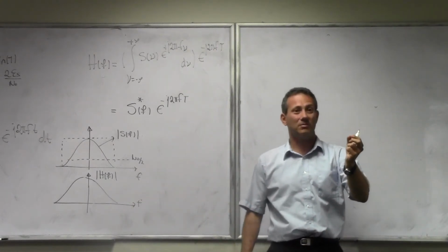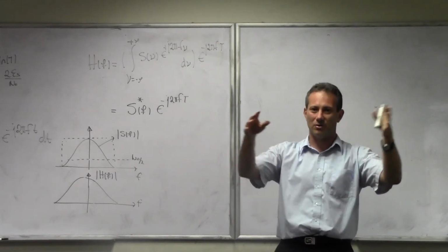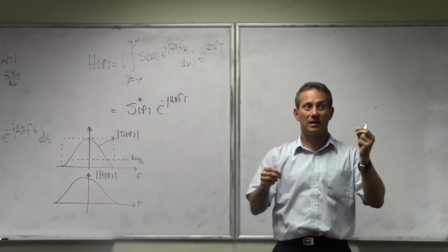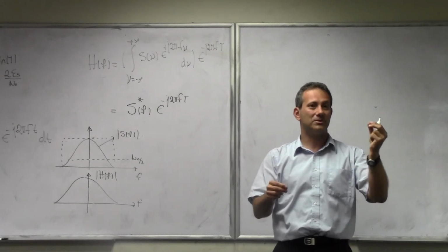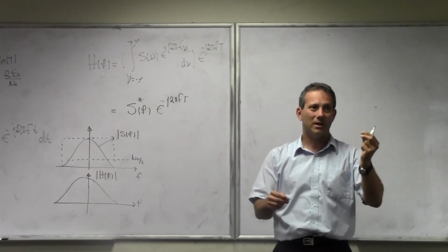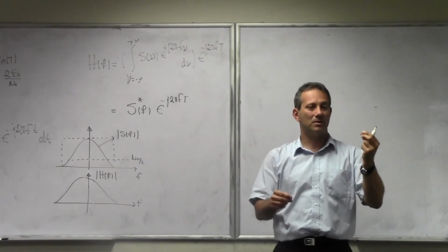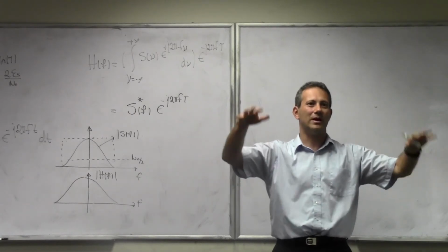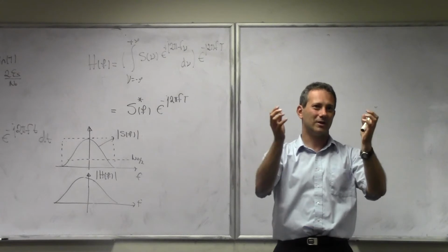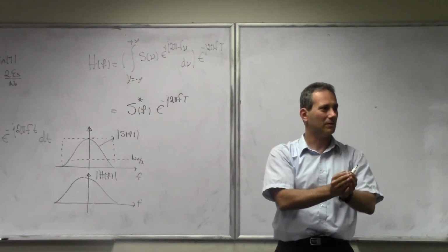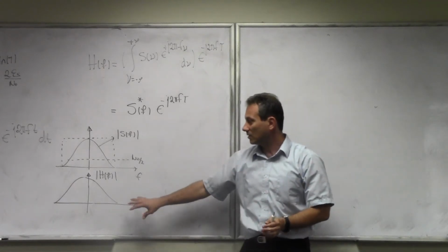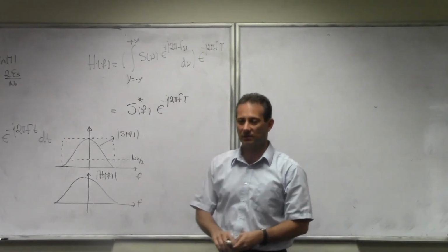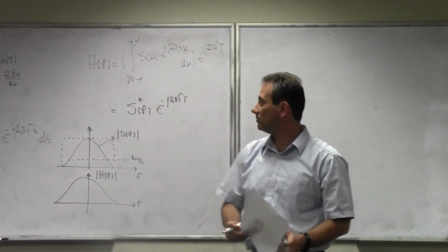And that's always going to be the case in a lot of problems that you encounter in various courses. You're going to find the task of maximizing signal to noise ratio. That's a really different task than preserving the signal. And whenever you try to maximize signal to noise ratio, it's always: where is it good? Give me more of that, and where it's bad, give me less of that. You're not going to try to equalize anything. You're really greedy here. You're trying to maximize and use where it's good. You're going to use more of it. And the consequence of that is the signal is not going to be preserved. But since that's not the major objective, we just need to make sure that we know how to make decisions.